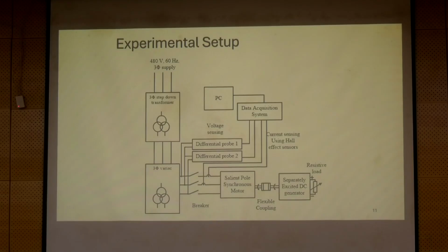So one thing you will notice is, I have used a differential voltage probe, because that's how you can measure between 2 lines. And I have used a Hall effect current sensor, which is a clamp-on current probe. And these probes will have their own attenuation factors. So the differential probe was set to measure 500 volts and translate it into 1 volt. So it's a setting of 500 to 1. The current probes were set to 10:1 basically. So 10 amperes of current would be converted into 1 volt. That's the idea. And all this data has to be sampled and acquired for data processing.